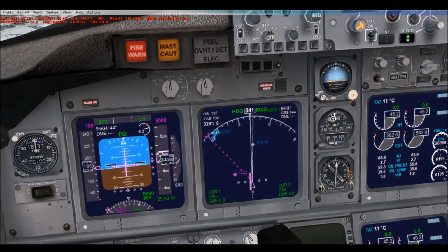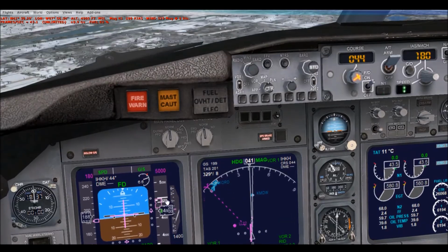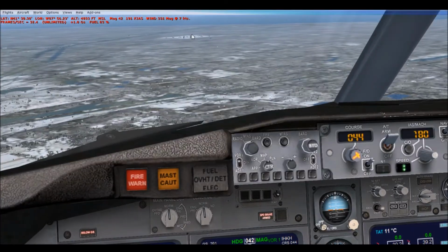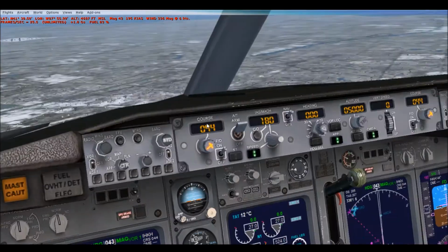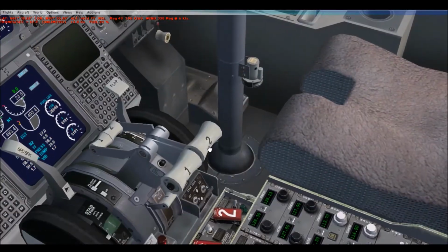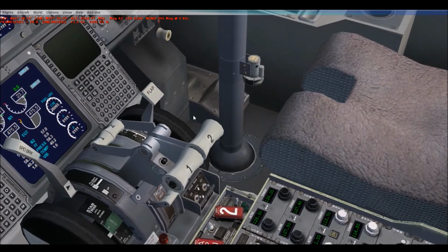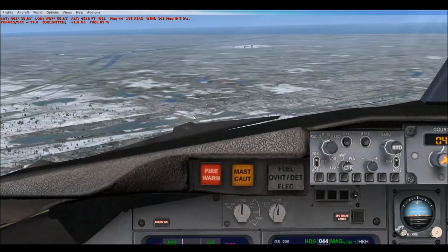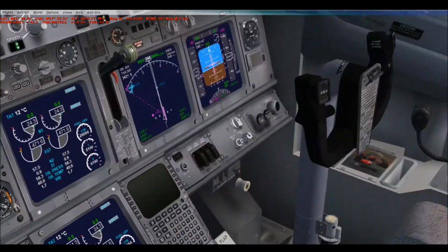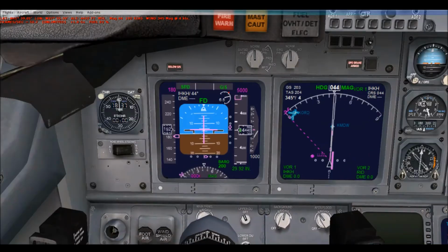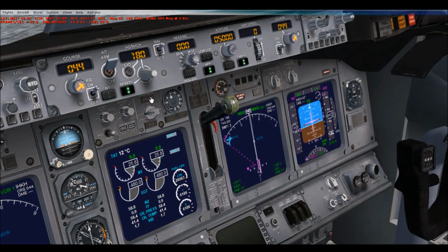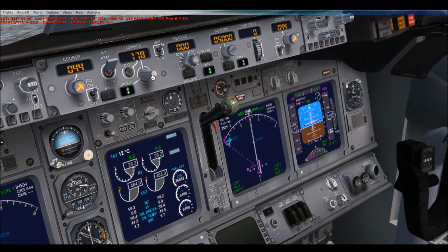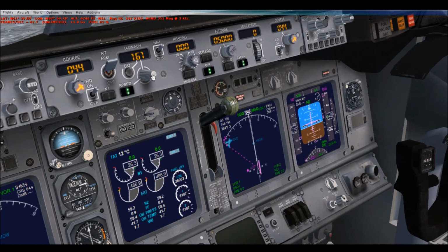You can see now it wants us to lose altitude because we want to keep that in the middle. There's our runways. We're going to line up right with this one right here. So we want to go ahead and start lowering our flaps, just so we can get ready for landing. You can see the diamonds are getting positioned right in the middle where we want them to. We can actually go ahead and further decrease our speed, like so.